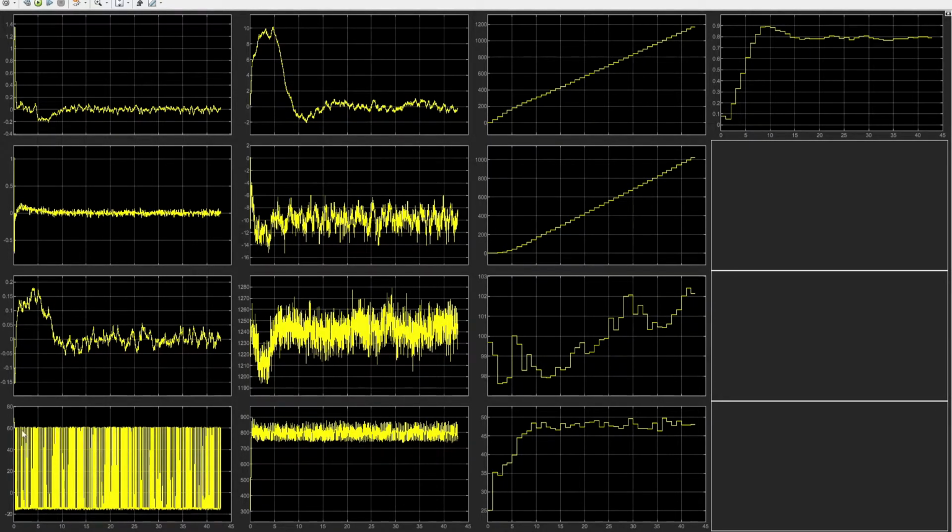We see that x is fairly constant except at the beginning, before it changes and heads in the 45-degree direction. And the y direction also accelerates at the beginning, and then levels out as it hits a constant velocity at 45 degrees. And with our Z accelerometer, we're at about negative 9.8 here, which is due to gravity.